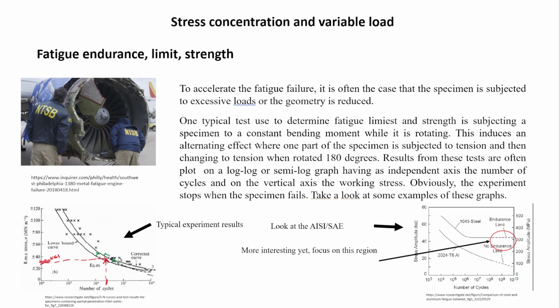Kind of, you start seeing where they fail. You increase the stress, the force applied, and then for sure, if you increase the force, they are going to fail earlier. And if you reduce the force, they're going to take more time to fail. And then they're going to have this kind of curve. This curve, where you plot the results of your tests, stress applied versus the number of cycles it took to break, usually takes this shape.